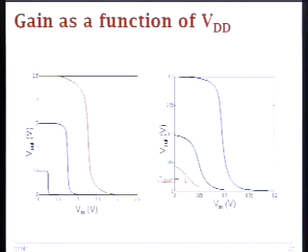And as you notice over here, this characteristic looks even nicer. It's sharper. It has a clearly defined transition in the form of this very high gain region. So now the question is, do you know why you have a shape like this compared to the high VDD?